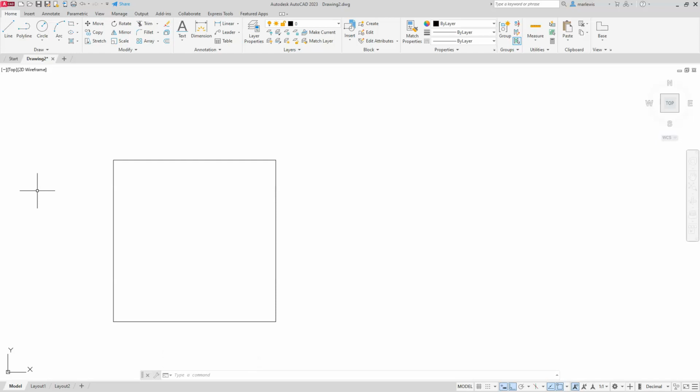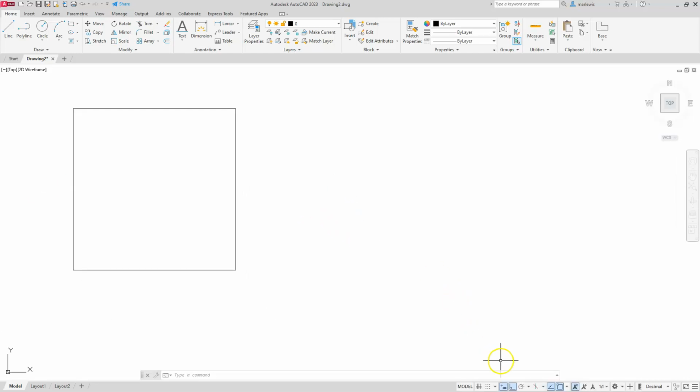All right, so the next thing, let's take a look at if we want to turn this box at an angle, especially an angle of 45. Remember that these two commands cannot be on at the same time. I don't care how you try it, it's just not going to happen. So if I go ahead and select this one, by default, this has to turn off. Likewise, if I select the ortho, the polar tracking turns off.